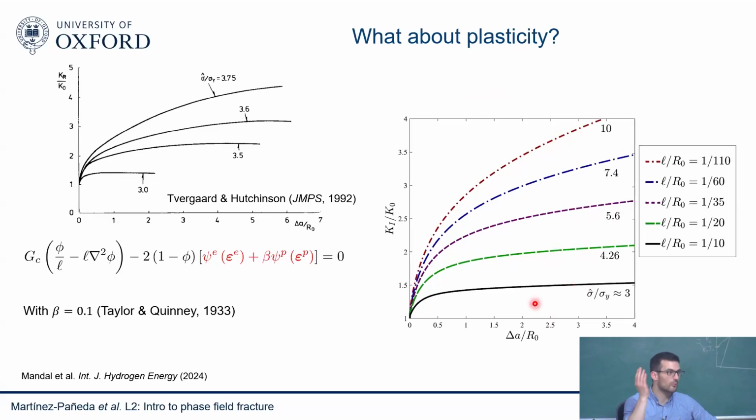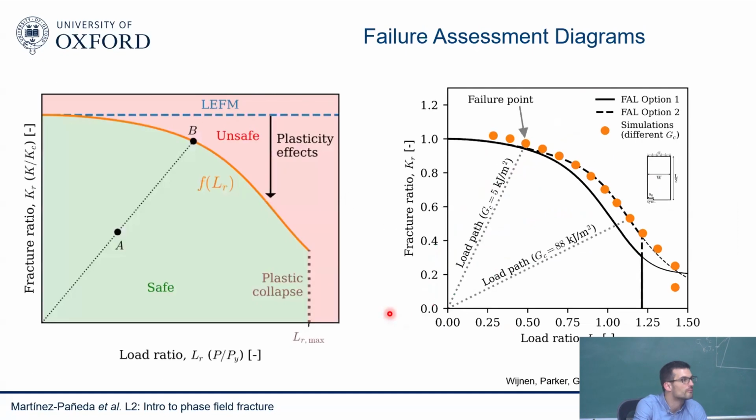And that also answers the other question that we were discussing before. What is the strength? What does fracture strength mean in an elastoplastic material, in a metal? Is it the grain boundary strength, or is it the UTS? Well, whatever it is, if you have experimental data, like that one, you could actually calibrate your L to fit that experimental data, because the only thing that changes here is L. All the other parameters you know. Cracking starts always at the same place. You know your fracture toughness. So the only thing that you don't know is how much plastic dissipation you have. And that will depend, of course, on your yield stress, your strain hardening exponent, but those things you know from a uniaxial stress strain curve, and your local fracture toughness, which you can calibrate with this. So that's another option. And then you know that you're dissipating the right amount of plastic work.